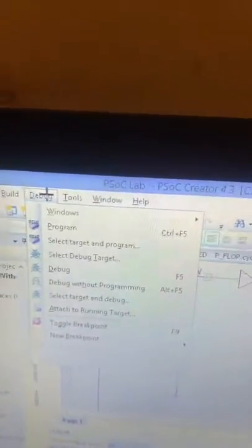So what I did here was I built my complete diagram in the schematic, and I programmed it using the debug tab right here. And as you can see in the loading bar, it's still building because I just inserted the PSoC board into my laptop. So here, once the build is finished, I can then debug it by programming it forward.